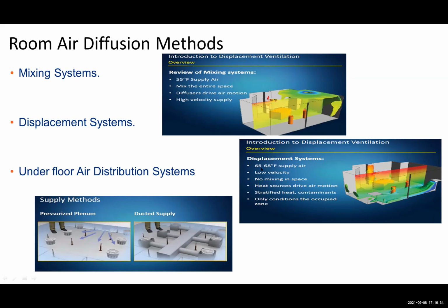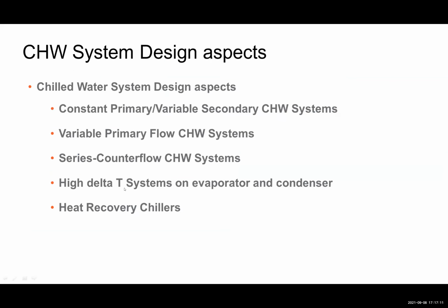to displacement system, because you see here, in displacement systems you have supply air at a higher air quantity, higher temperature, and low velocity. So the IAQ also is better. So many other advantages are there with different room air diffusion methods. So it's always good to ensure that the designers, the owners and contractors are all shifted to much better, more efficient systems that are technologically available today. So the underfloor air distribution.